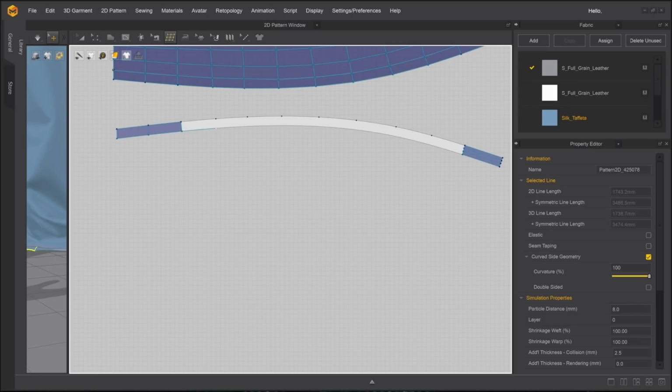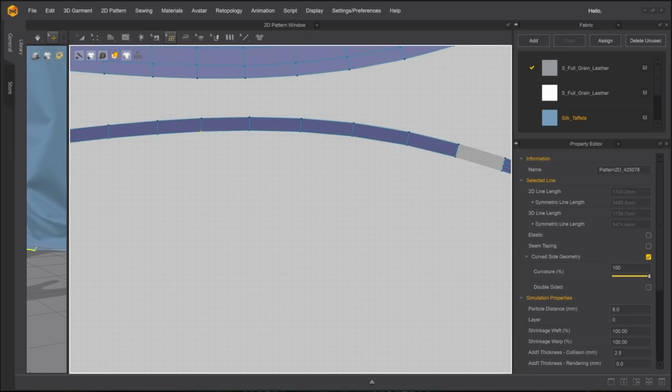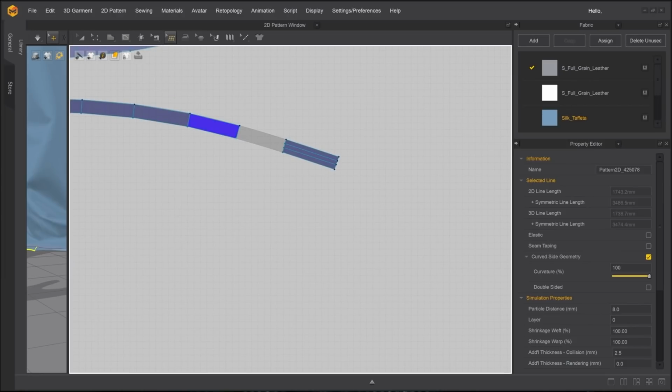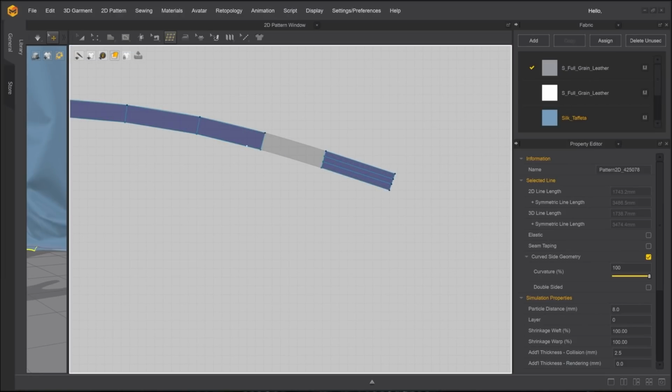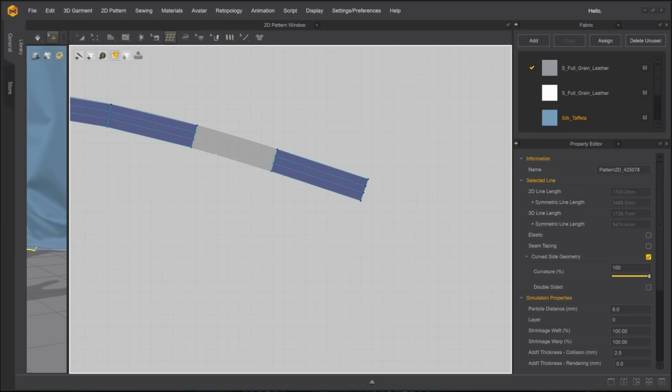I'm going to block out the larger quads along the facing first. Then I am using the Control plus Shift hotkey to automatically add full rows of edges so that the facing can have some dimension. And finishing off the strip by connecting the two sections.